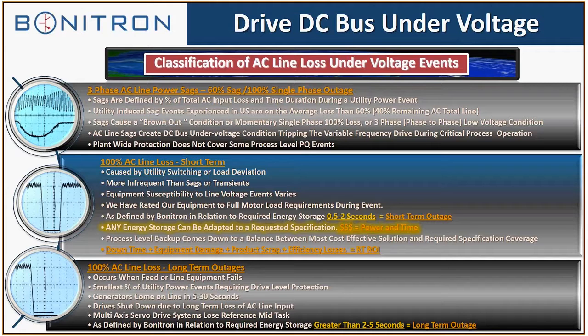Now what we've done is we've taken the sag ride-throughs, the single unit ride-throughs, and we've added energy storage to them. Either electrolytic caps if it's very low kilowatts, or ultra caps for the higher kilowatts and the higher times. Ultra caps, we usually say half a second to 2 seconds if we're using the sag booster. And that's how we define short-term outage. It's not really an industry term, it's pretty relative. It just is defined by the types of energy storage we use.